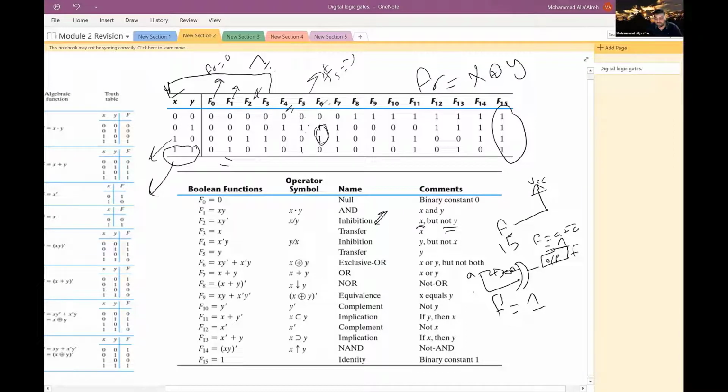But you don't need to do that. What you can do is simply take that output pin F, go to the logic, look at the primitives, and look for something called VCC. VCC indicates the high voltage. In our case, with current computers, it's plus 5 volts.